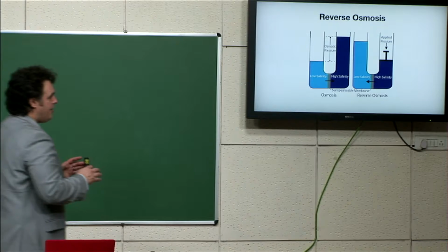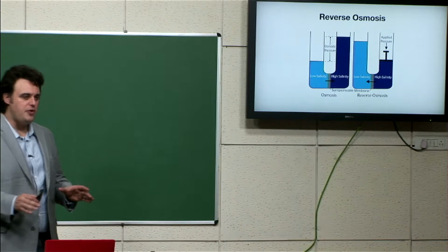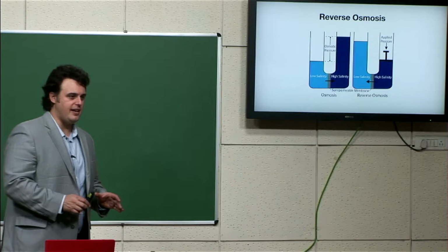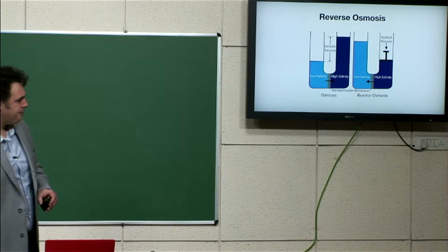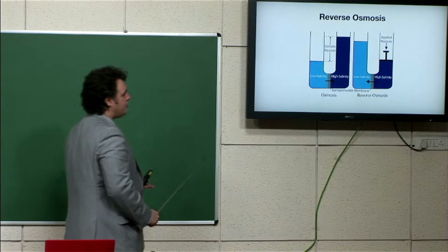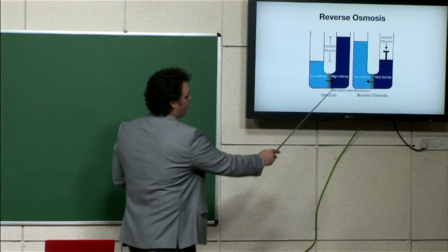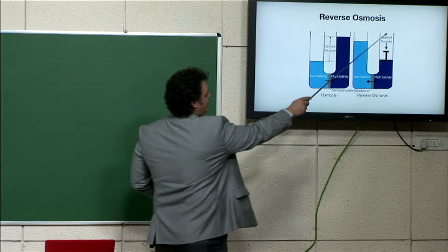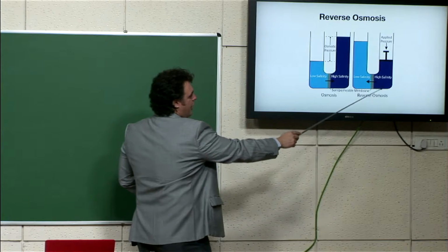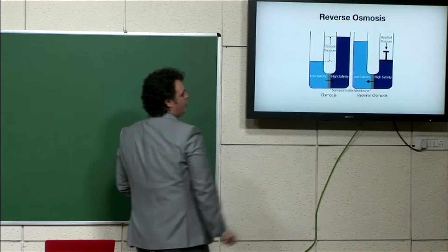And the de facto solution would have been reverse osmosis. I bet most of you have an RO system in your house, right, in the kitchen. Yeah, it's very, very common, particularly in middle class and above households here. The way that works is it's the opposite of the osmotic process, which would draw low salinity water into a high salinity solution. Instead, you can use an applied pressure and drive that water backwards. That's the reverse process to make the low salinity water.